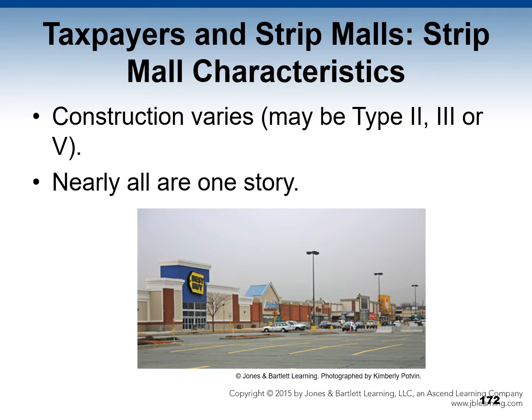Let's go into a little bit more detail with strip malls. Some characteristics of strip malls is that they may be of non-combustible, ordinary, or even wood frame construction, types 2, 3, and 5 construction, respectively. When made of non-combustible construction, strip malls have exterior walls of concrete block or concrete "tilt walls," possibly with brick veneer, with steel bar joist roof members and a metal deck supporting a built-up roof. Contemporary ordinary construction strip malls use concrete block for exterior walls and solid wood joists or lightweight wood trusses to support a wood roof deck.